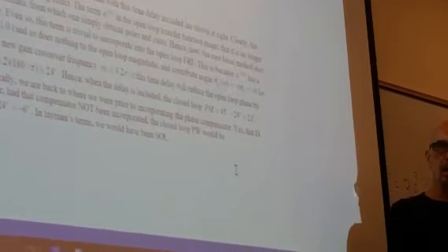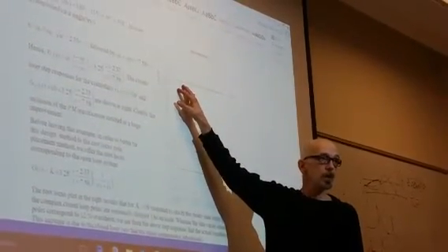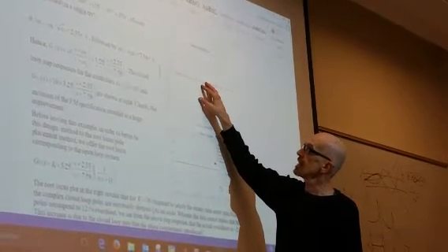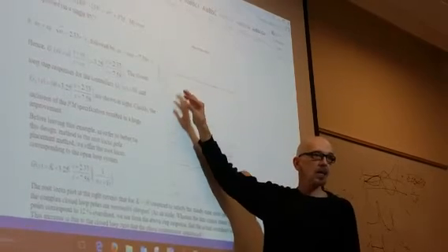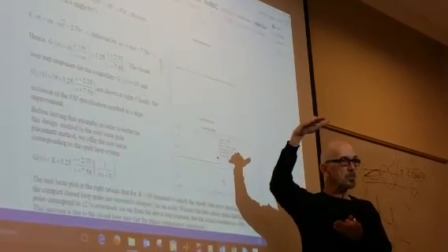Remember, the original phase margin was 18 degrees before we incorporated the lead compensator. Remember? That's back up here. We did this with lead compensation alone. We had this 21 degree phase margin, or 18 degree phase margin. Yeah, it looked okay. We achieved the right steady state errors and everything, but it oscillated, so we said, let's throw a lead compensator in there and raise up the phase margin.